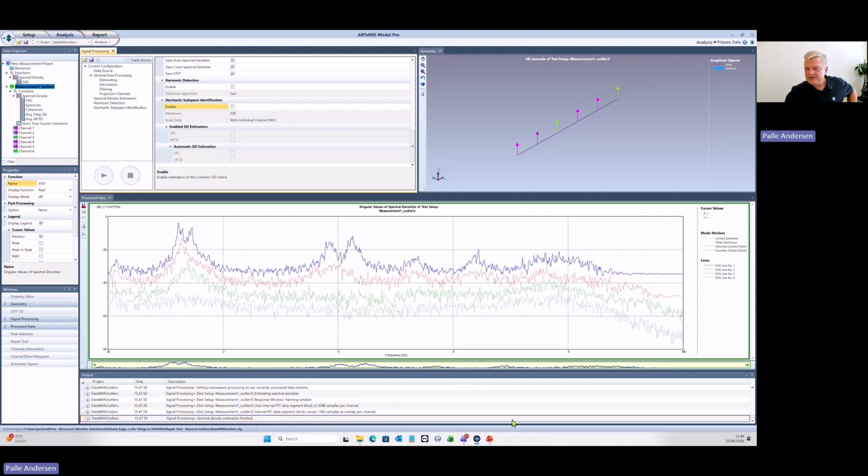So now you can actually see here, this is then the SVD diagram of the data that has all these outliers. And maybe you can observe there is a flat line here. So it's actually indicating that we have a kind of a noise level that is probably at this level here. At least we have a lot of noise generated because these spikes, they are really sharp in time domain.